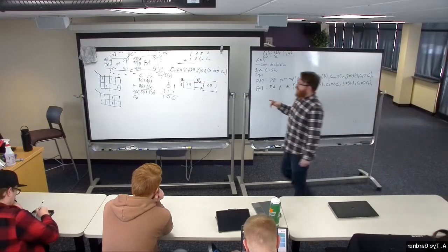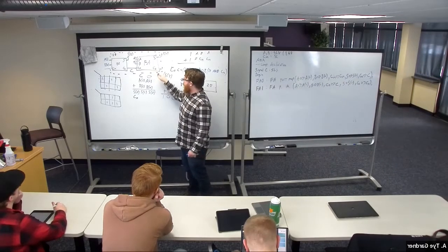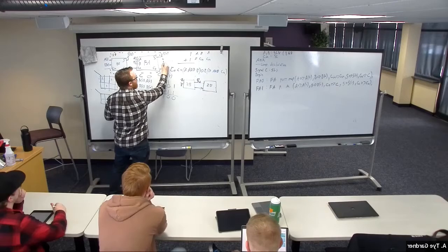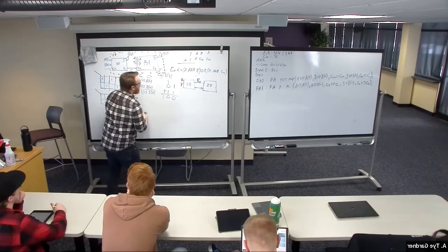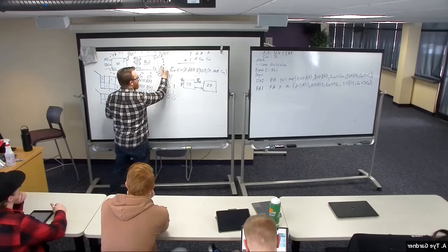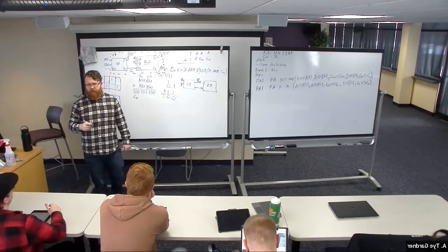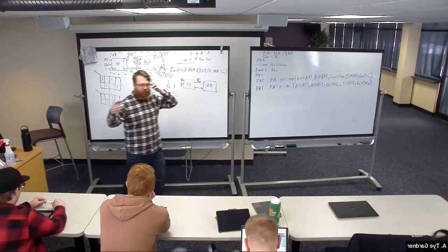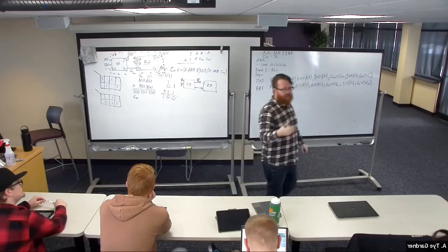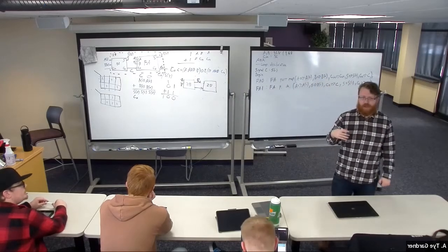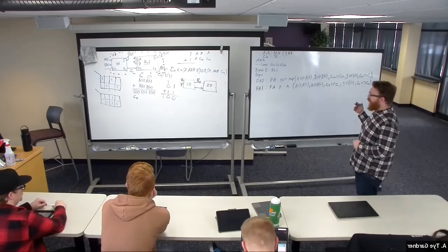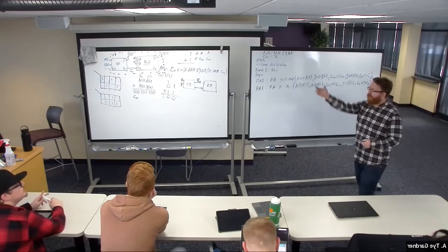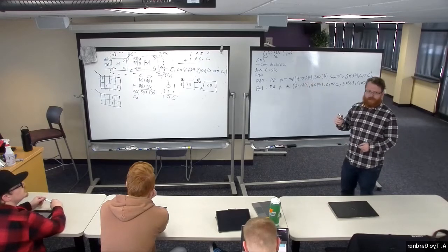Because all that's saying is that my port for full adder is CO, and then the port level, let me do this real quick, here is also called CO. I have a port called CO, I have a signal called CO, and then a port called CO going to that. It's the same thing called a bunch of different things that are connected together. So we need to keep track of these hierarchical port connections in our minds, and it's okay to use longer port names if it helps you, right? I could call that CO underscore 2B for the 2-bit.